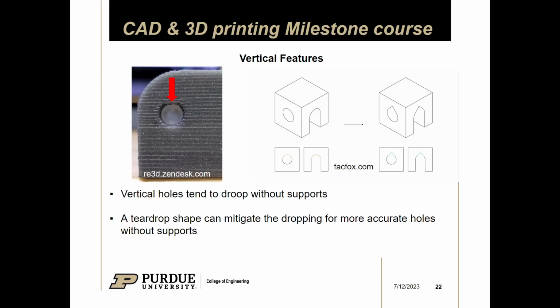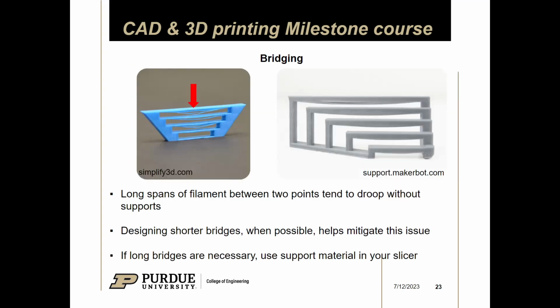Yeah, so this is something to keep in mind. These are all just overhang stuff, but overhangs will sneak into places that you don't expect. Bridging is also a limitation of 3D printers. So you'll see that when it makes long bridges, it starts to droop, right? The plastic is drooping just because gravity will pull the filament down before it gets to cool. And if you have really long bridges, then your prints won't turn out as nice.